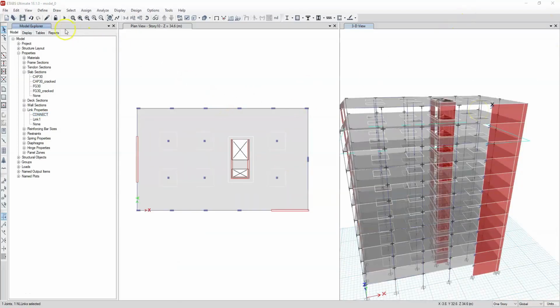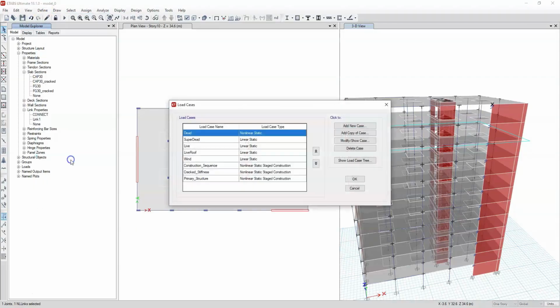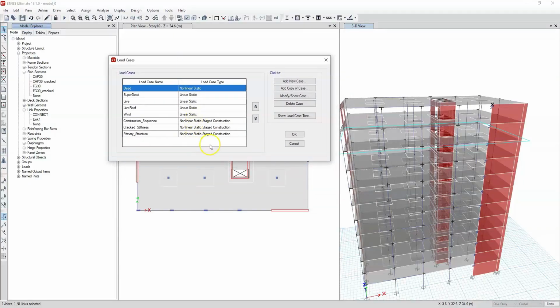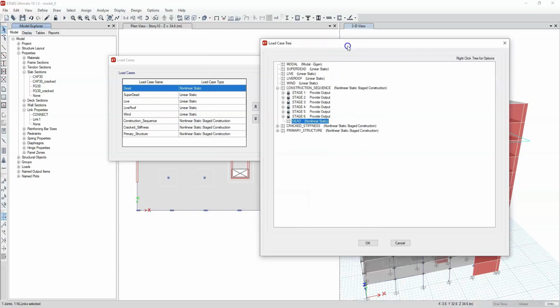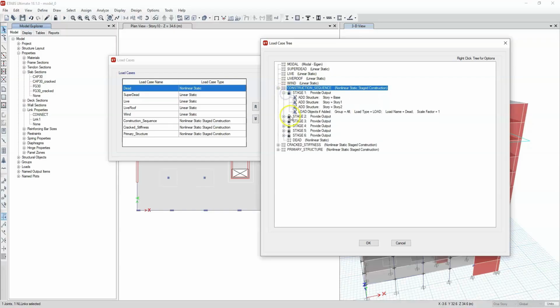Another very important aspect to comment on is how the construction of the analyses for this model was conceived. With the concern of calculating the structure, we have to create submodels. Essentially, we have created 3 submodels. One of them has an objective that is not specifically related to seismic analysis, but rather to obtaining more suitable and correct results for permanent loads.